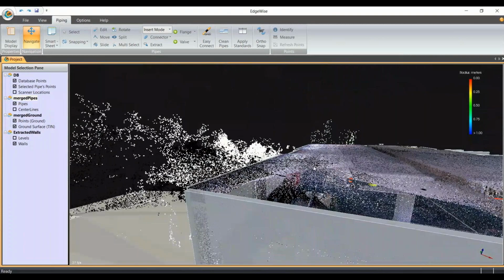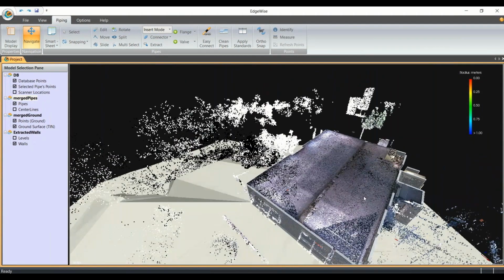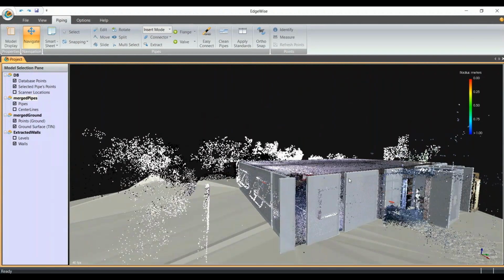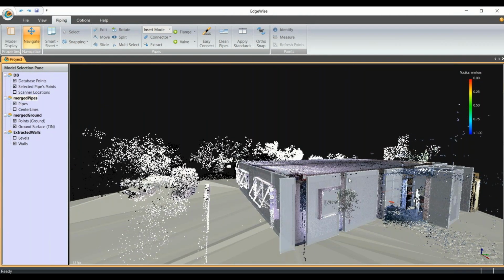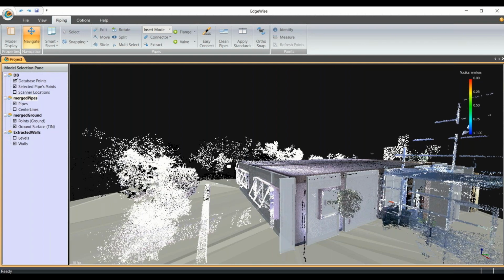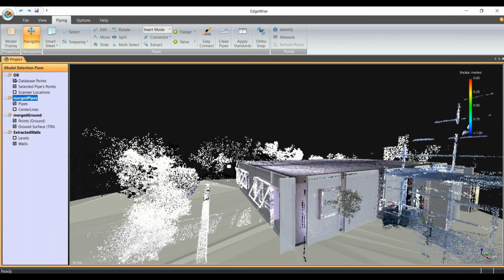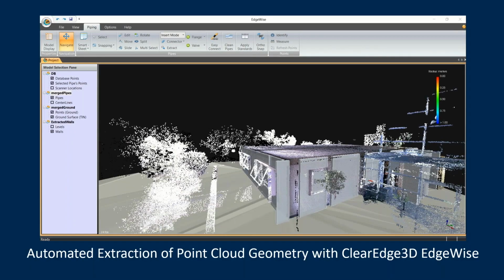You'll see there are a bit of gaps here and there. That comes again with the point cloud, the density at that point, or whether the light refraction was a bit too much, so it wasn't as dense to extract, but you get the idea. If I switch it off, this is what it had. Now, if I wanted, I could simply sweep one wall there because that is one continuous wall, or I could go and edit that in Revit. It's totally up to me.